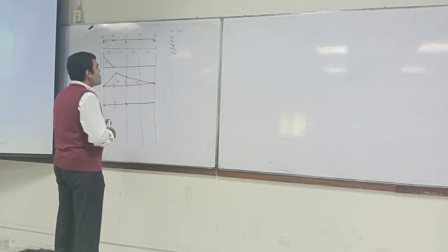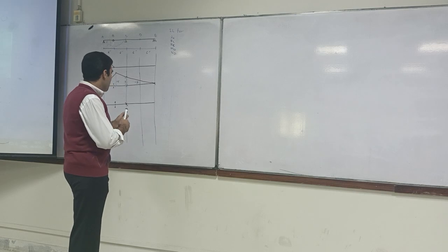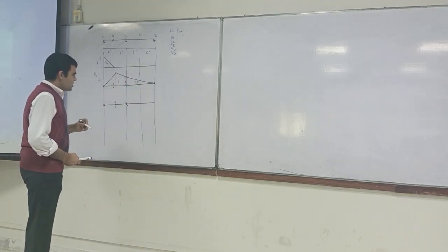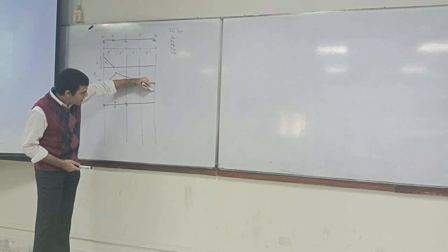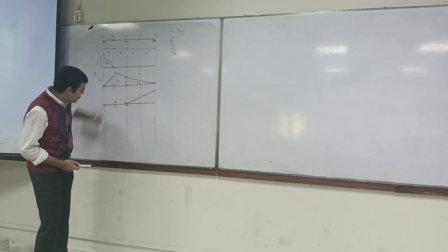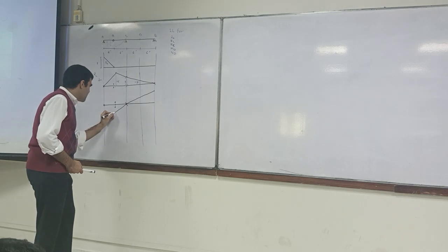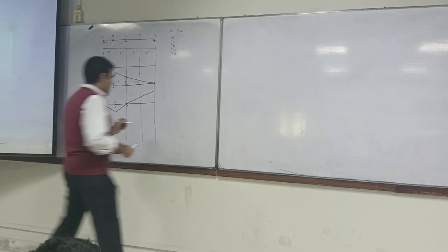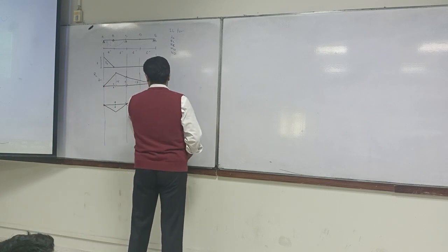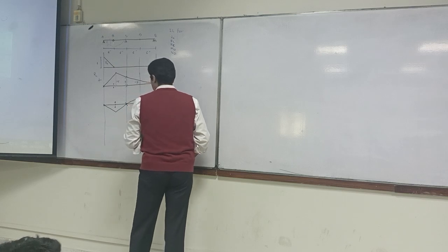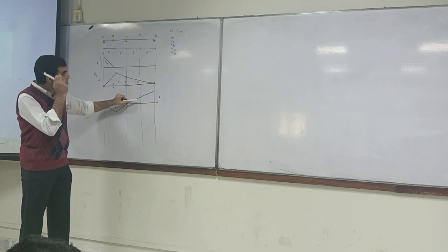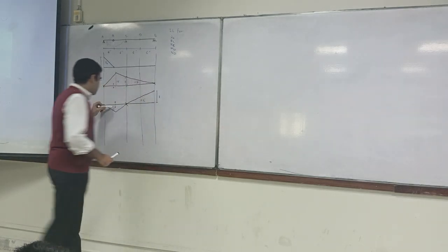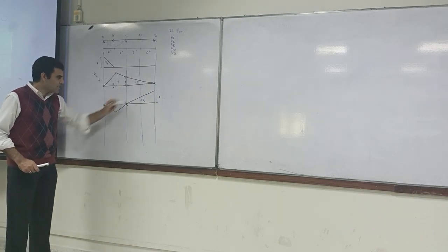So remove the ability to resist reaction from E, and that will come over here. Now we must join this by a straight line. Please remember, don't break the member or bend it, and it will be going straight, and then it will become like this. So this is one. This is 1. You can easily find out 1 by 12. This is 1.5. This is 0.5. So this will be 0.5. And similarly, you can find out this one, because if you know this one by similarity, you know this one, and I think this one should also be 0.5.